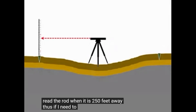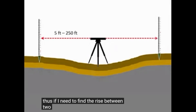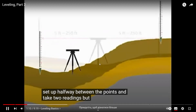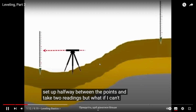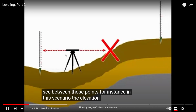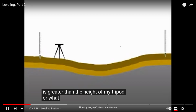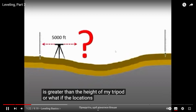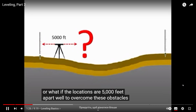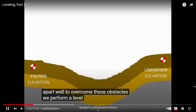Thus, if I need to find the rise between two locations 500 feet apart, I simply set up halfway between the points and take two readings. But what if I can't see between those points? For instance, when the slope is very big, or the elevation difference is greater than the height of my tripod. Or what if the locations are 5,000 feet apart? Well, to overcome these obstacles, we perform a level circuit.